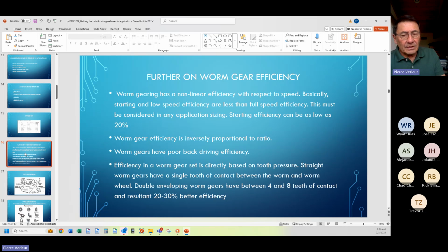We are always going forward in the current discussion. The difference is that I'm applying motor torque, positive motor torque to move forward, versus the load is applying torque back against the motor. We're still going in the same direction. An example of that is driving a load up a hill, in which case we're going forward and the motor is applying torque to the gearbox, and we're getting the efficiencies of the worm gear as published.